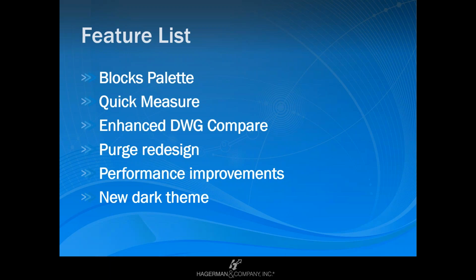The DWG Compare, which was introduced last year, has been enhanced. We will show you that. The Purge command, finally, after all these years, they've updated the utility itself. The dialog box has been greatly enhanced, and they've added a couple of new features when you're looking for blocks that are inside of a drawing. They're used, but maybe you can't find them. You're going to see general performance improvements, and they also have updated and modernized the background, your coloring scheme.